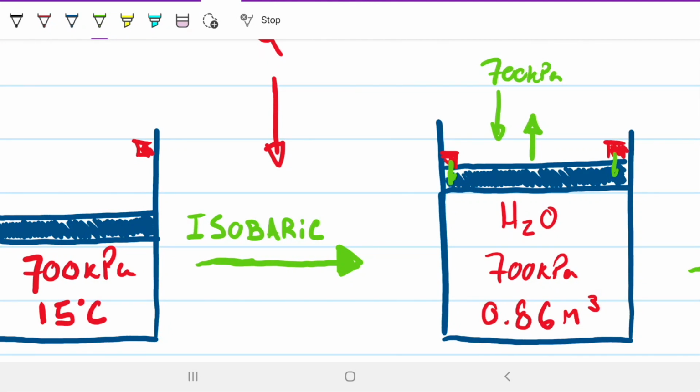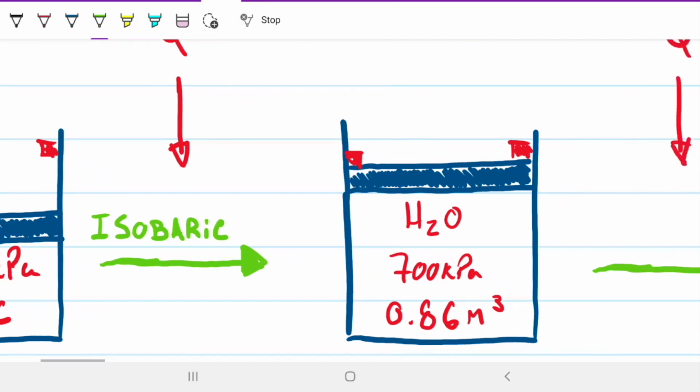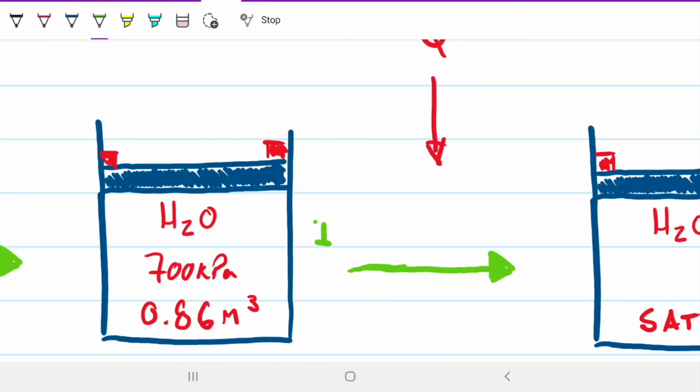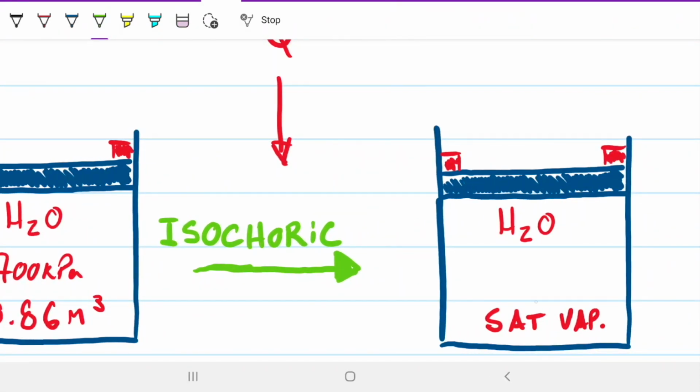So that means that the volume can't change, right? And if the volume can't change, what's going to change is the pressure, right? I'm going to have an increase in pressure inside my steam here until the heat addition process is finished. But because this piston cannot move upwards, we know this is going to have the same volume at the end of the process, right? So this is an isochoric process, also known as an isovolumetric process, depending on where you guys are. Okay, so isochoric or isovolumetric. So we can be sure that this is a saturated vapor because it says so in the problem statement, but we can also be sure that this volume here is the same volume as V2 on state 2, right?